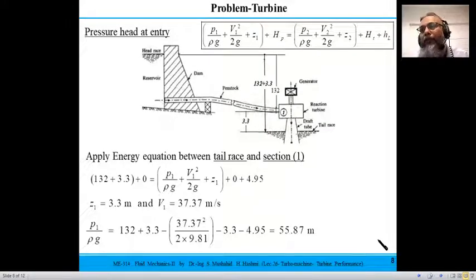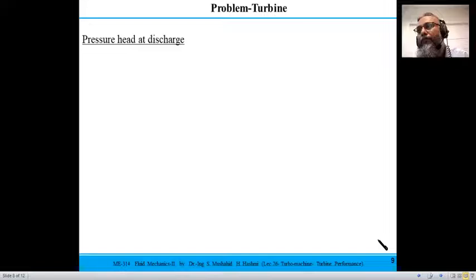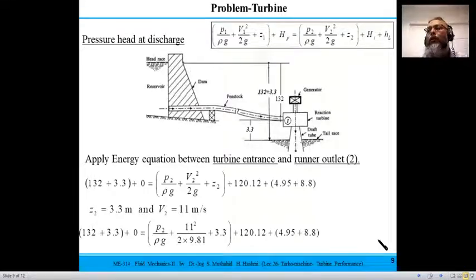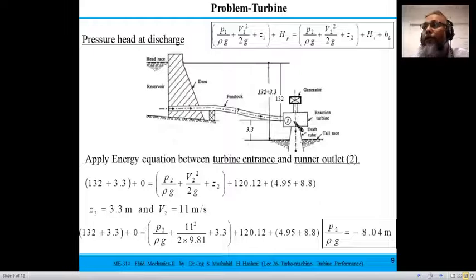So this difference is the pressure drop that takes place in the runner, and that is a feature of the reaction turbine, because some of the available pressure energy is converted into kinetic head in the guide vanes, and then the energy transfer takes place due to the pressure drop in the runner. Because that's a negative pressure versus a higher pressure, this pressure difference forces the fluid to move into the runner, so that the energy interaction takes place.